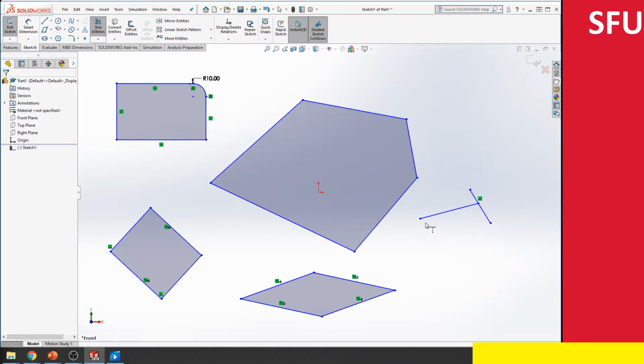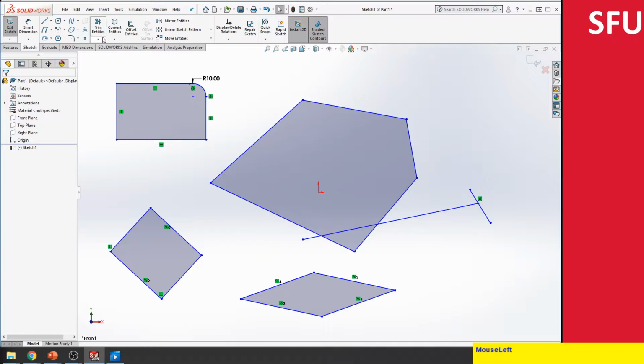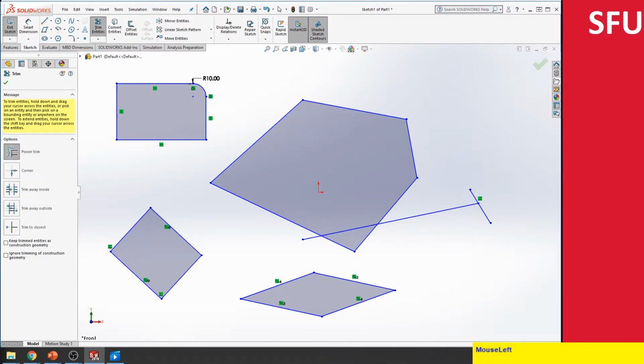We can do the same thing with trim. Let's say I happen to have this line a little bit longer. What I can do is click on trim. As soon as I click on trim, it gives me the option of what's known as a power trim. This is the default, so we'll keep it at power trim and see what it actually does. Notice that I'm holding my mouse down and it draws a line of how things are going to get cut.